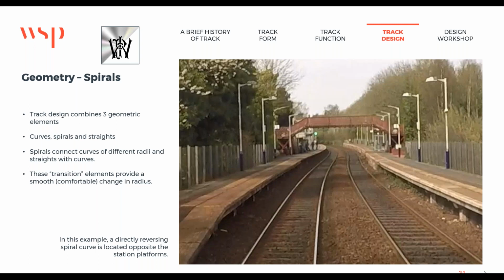So as a designer, I'm trying to combine elements where I can. I'm trying to see what the average curve radius is. And in fact, that's what the design software looks at when it does regression. It looks at the various radii that have been surveyed, and it tries to pull a single radius out of there, which is an arithmetic average of all the radii together over that given length. And hopefully that will be able to be installed with the minimum of track slews and lifts.